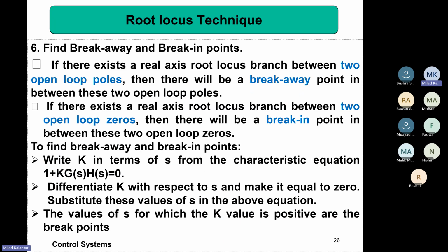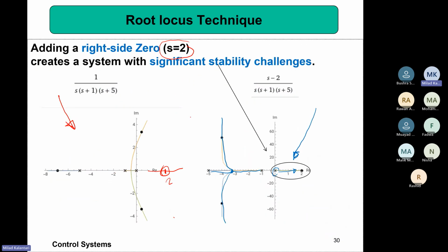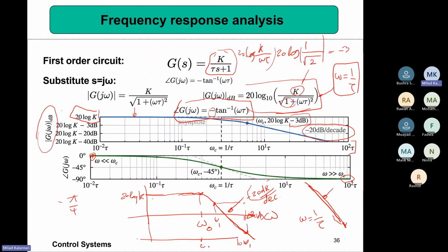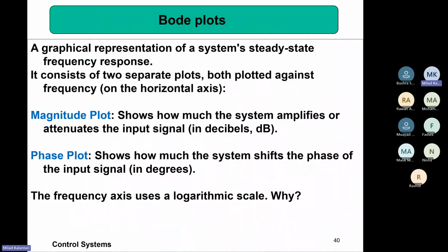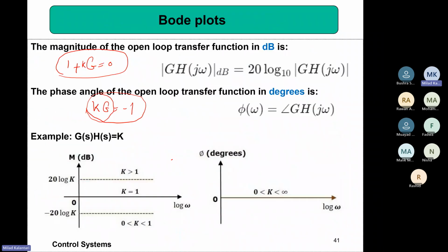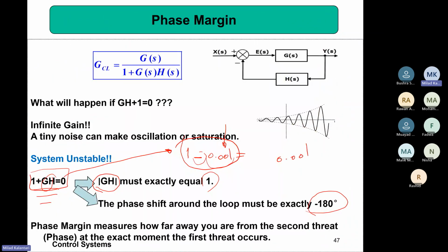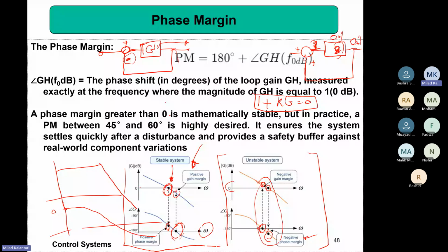So basically, you need to work a little bit with these three techniques to find the stability of systems: Routh, which is based on the polynomial; root locus, which tries to estimate where the roots are moving; and then the Bode diagram, which is a bit more useful for our circuit design because we are trying to understand where the system sign is changing and negative feedback becomes positive. You can think like that.